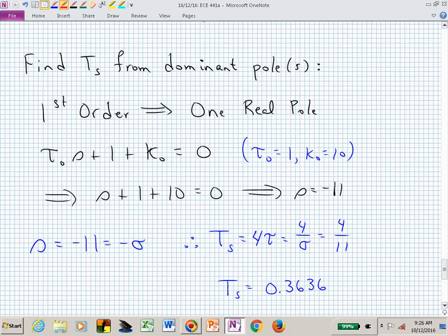So even though, remember that crosshatched section of allowable region in the S-plane, somebody's going to get smart on me and say, I just made mine minus infinity plus and minus j infinity. That's where I put my pole. That's in the allowable region. Yes, it is, but it's not physically realistic. So there are bounds. We can't go too far into the complex S-plane.